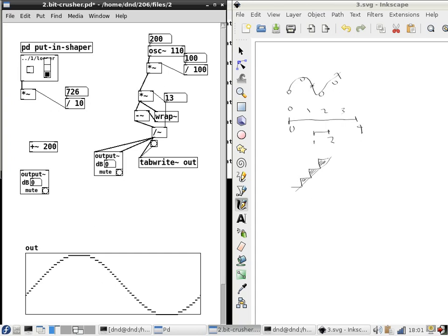Or if you're operating in digital, on a file, just drop the lower byte of the sound file, reduce it to 8 bits and then push it back up to 16 and play it, and you'll hear a nice 8-bit sound file. So making an 8-bit sound file is essentially quantizing the voltage in the sound to the nearest of 256 possible values. That is equivalent to taking the sound, multiplying it by 256, and then taking the integer part.